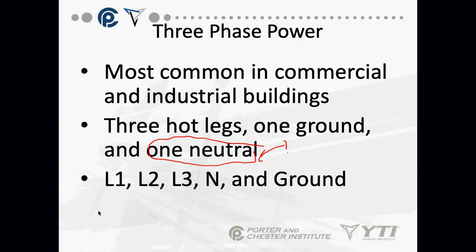Okay, what color wire is ground? Green, or solid copper, bare wire with no insulation on it. It will never be white. That's neutral. So again, if you have a neutral, that's going to be a white wire. Ground will be green or just bare copper.